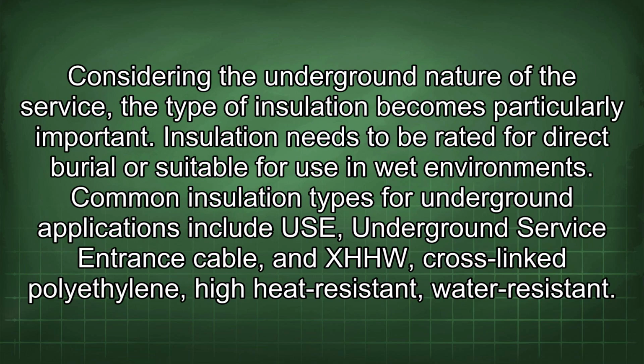Considering the underground nature of the service, the type of insulation becomes particularly important. Insulation needs to be rated for direct burial or suitable for use in wet environments. Common insulation types for underground applications include underground service entrance cable, and XHHW, cross-linked polyethylene, high heat resistant, water resistant.